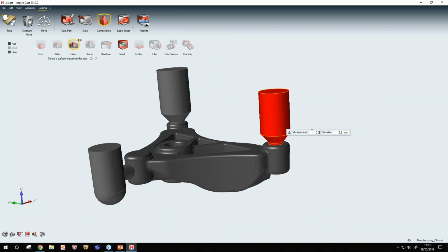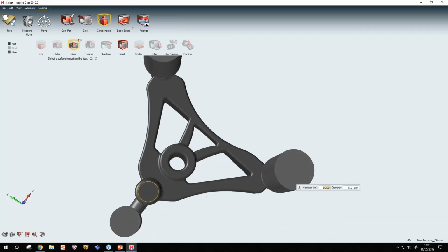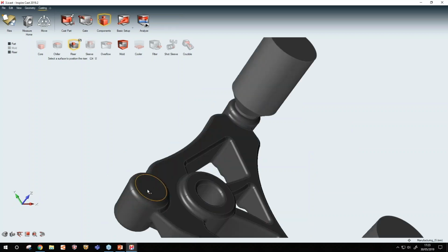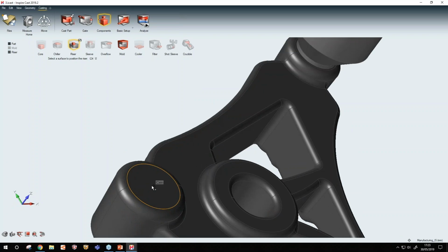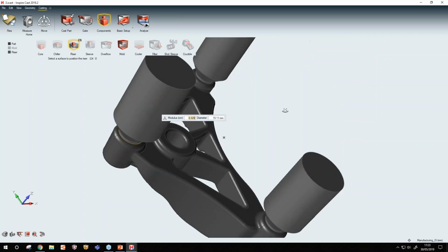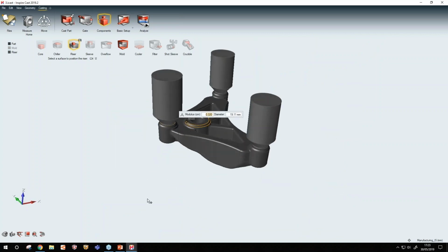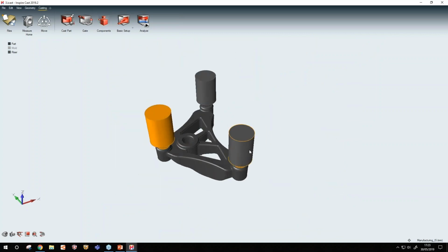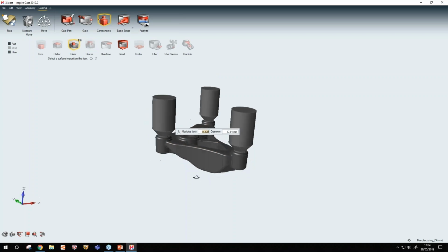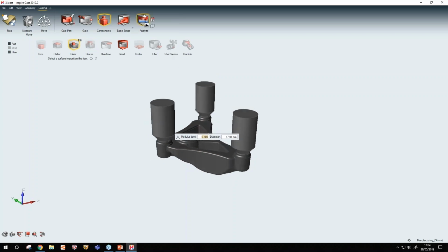I will use a 0.3 here also, and I will remove this riser, and I will create a new one, even bigger here, 0.32. Okay, to try to compensate, because this region is bigger. Now let me use a 0.3 riser. I will leave it like this, 0.3. 3 risers with the same size to compensate the porosity.